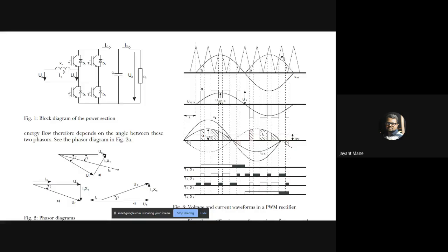and we know that for comparison there is some logic. So logic means there could be carrier greater than reference, or both equal, or reference greater than carrier. So what should be happening? That depends upon whether on the inverting terminal or non-inverting terminal we connect the carrier or the reference.